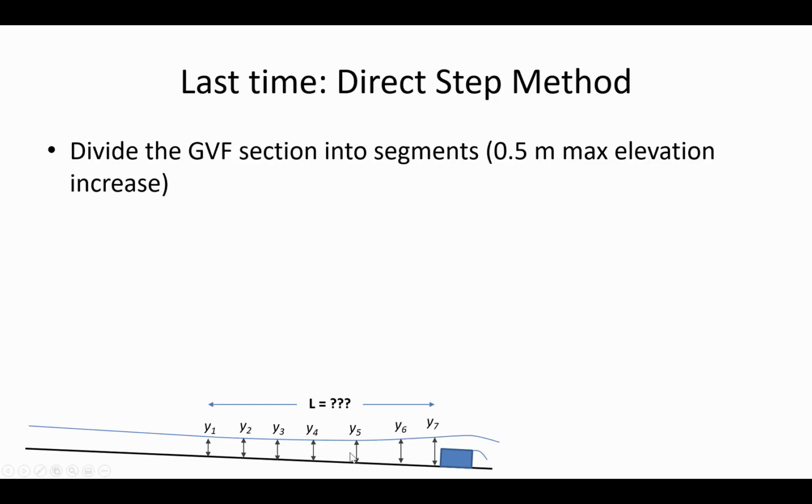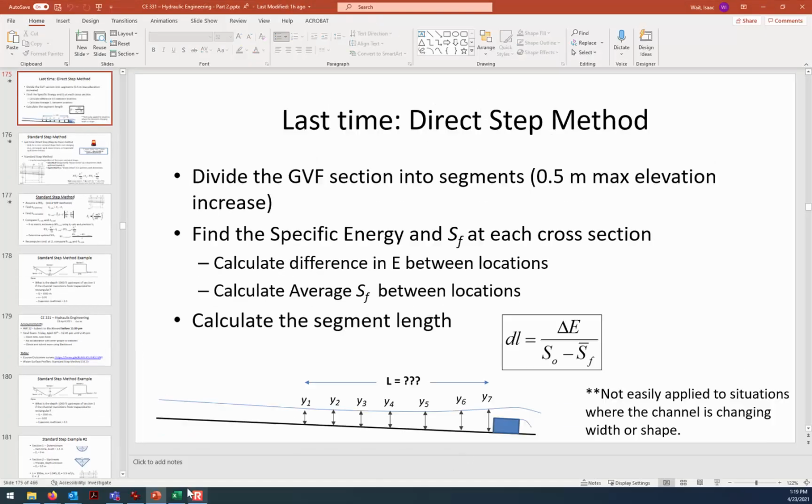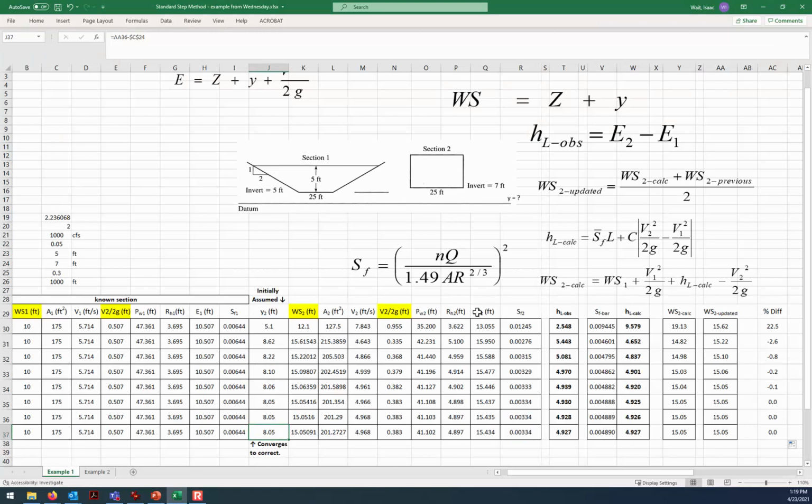But there's less error if we break it up into segments than there would be going with one big jump between the 2 points. So it's a similar idea in this example, where we're assuming a linear change in the water depth between these 2 sections, but hopefully the sections are small enough and close enough together that we're not introducing too much error. Any questions from this example?